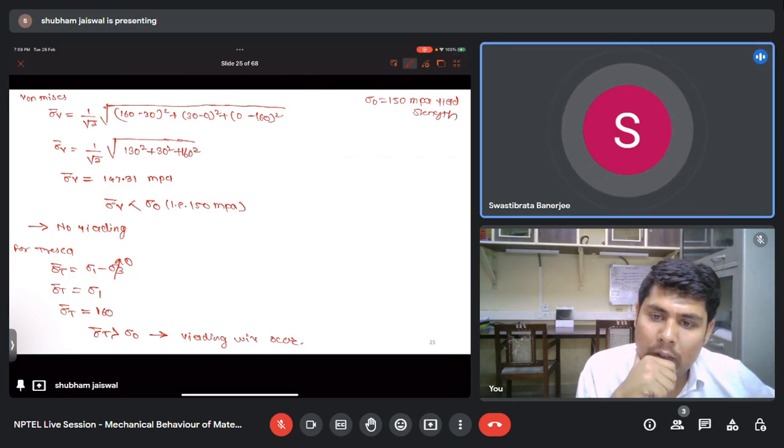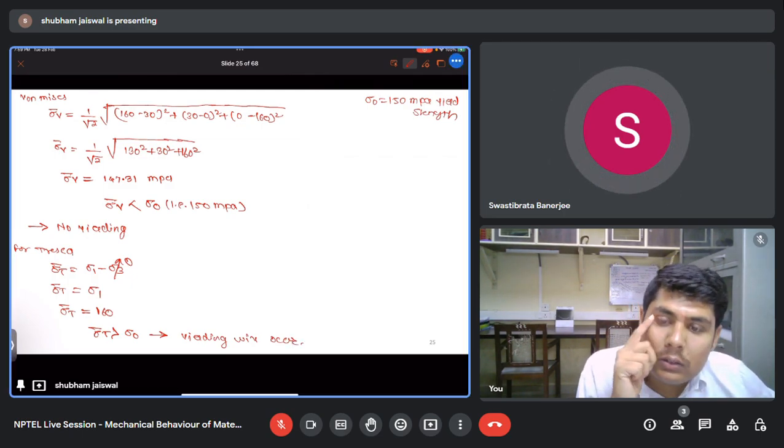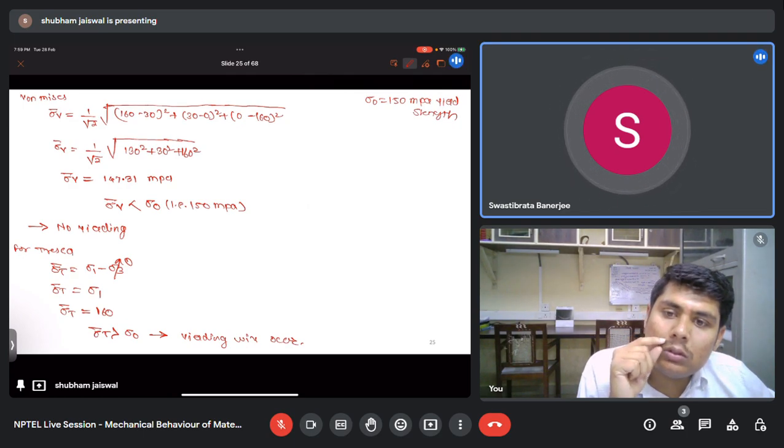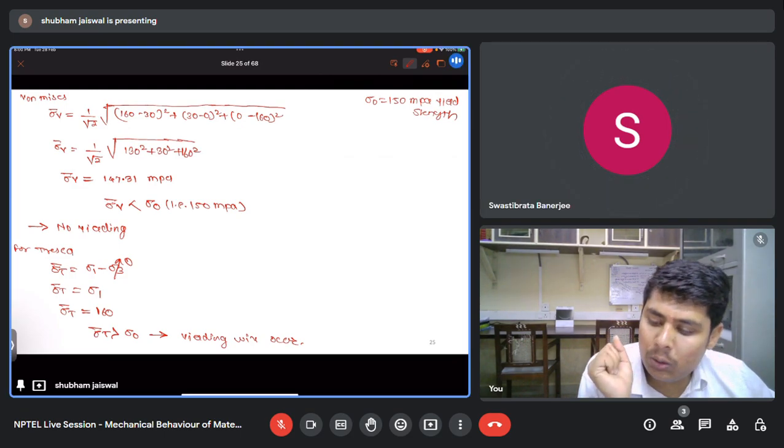Sir, for Tresca, as in the given question sigma 3 is already 0, so we can easily find sigma 1, sigma 2 or sigma 3 from the principal stress equation. So can we do that? Yeah, you can do that. Okay, okay, sir.